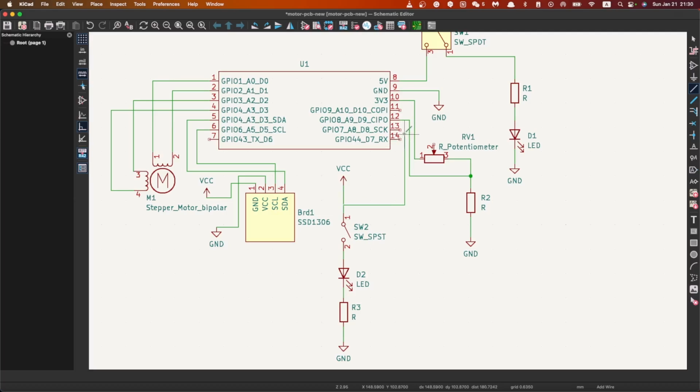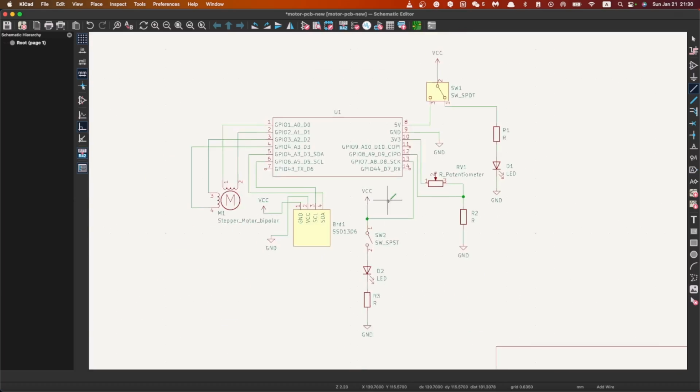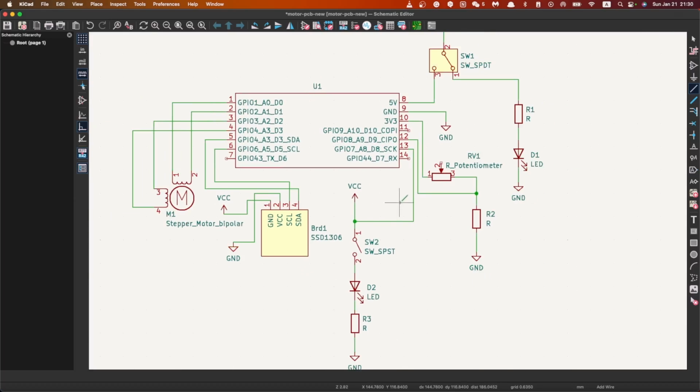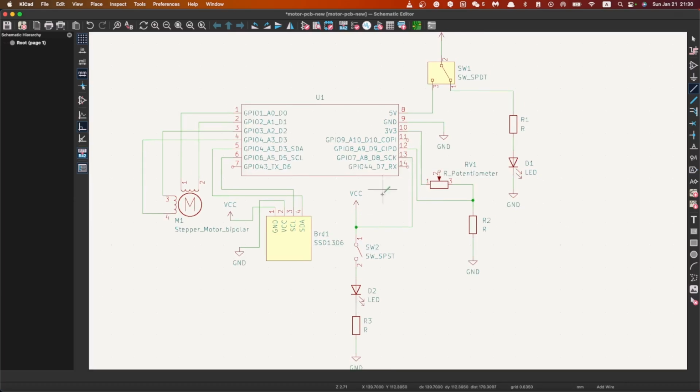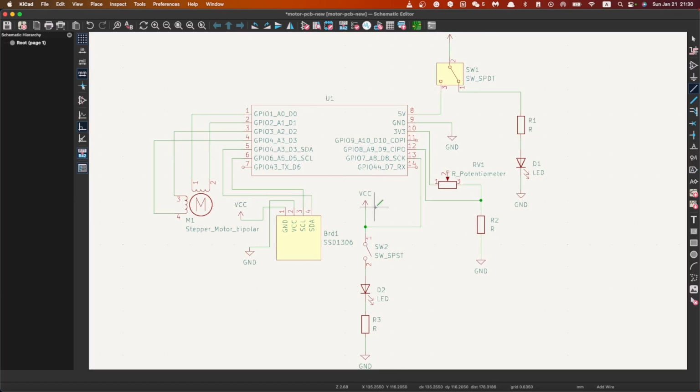Okay, and I can actually, should I do this or not? I think this is fine, but not really ideal, because this VCC here can be larger than the absolute maximum rating of your analog input or other inputs or outputs.